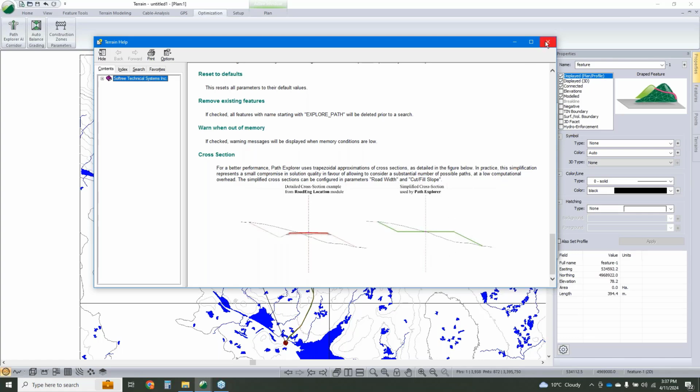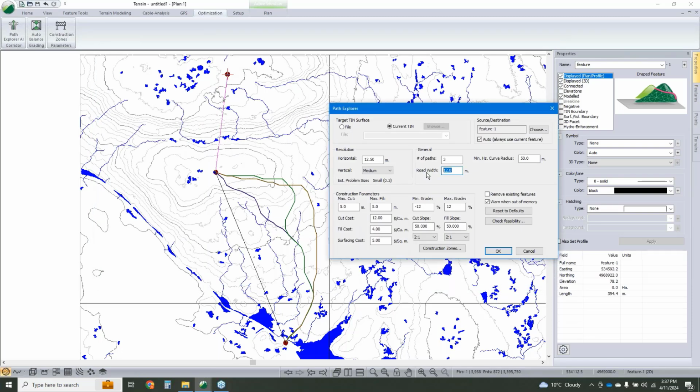We're broad brushing it to keep it as simple as possible, so it's a solvable problem. If it's the difference between a 10 meter wide or 12 meter wide prism, I'm probably not too worried about the granularity of that. And same with our cut and fill slope angles. Most of the time, I'm quite content running with the default settings here.